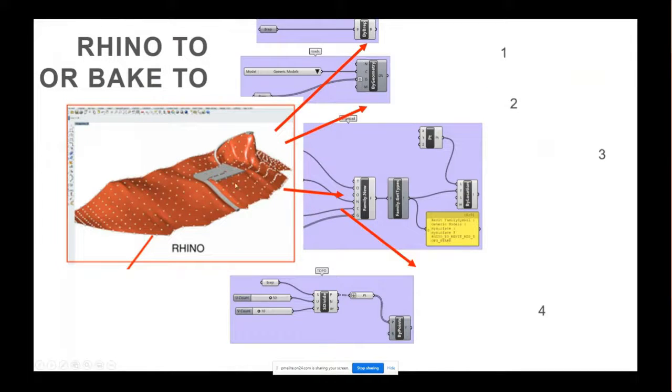I would take the block, let's say it's, whatever it is. Maybe it's a statue up on this observation platform up here. I would actually take that block, I would place it inside a family template using this new family node, and then I would place it using Rhino.Inside.Revit inside of Revit.